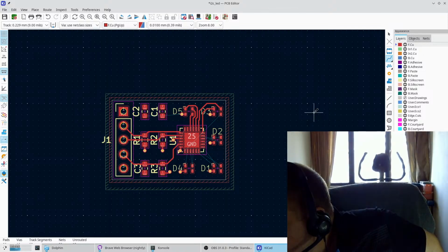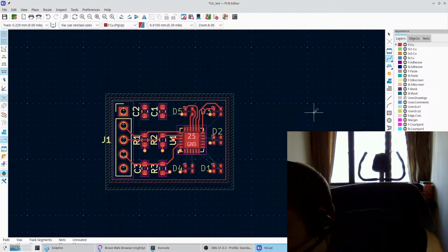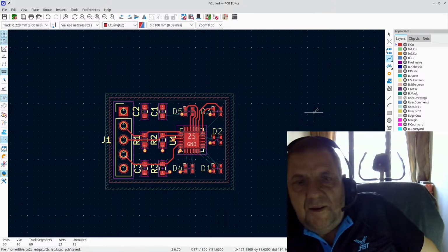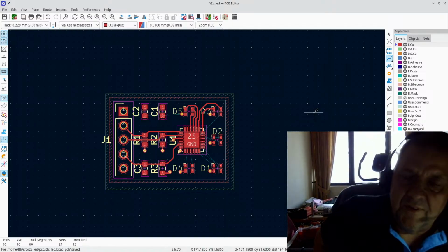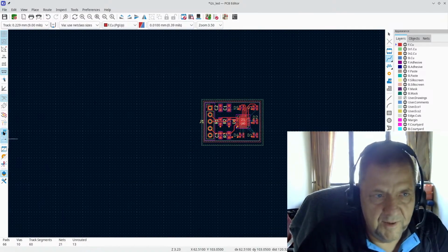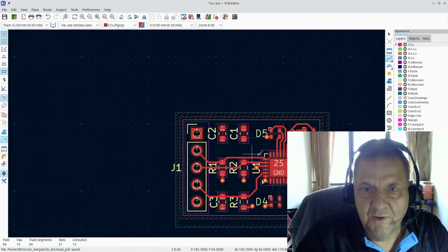What? There, I can see now how these layers will reduce the number of traces on the top border. Each of the 4 layers is insulated from each other. Yes, yes. It's just a... if you flat fill it, a layer is just a layer. But if you put these zone fills in, it basically fills up the layer. You can see over here, you can toggle between them.